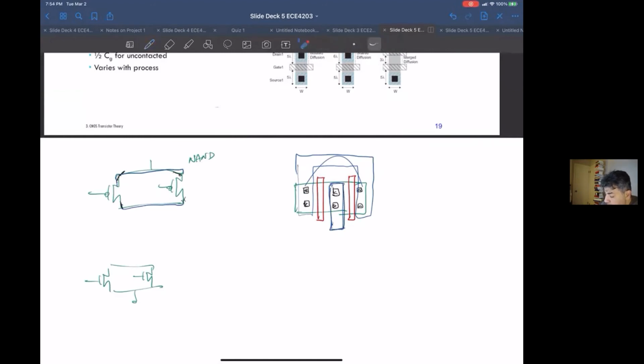Now, because the transistors are symmetric, I can make this the drain and this the source. Okay, so I can make this node, this node. So let me just redraw this thing. In the case of PMOS NAND gates, these would be their drains, and this would be the sources. So either I can make this merged node, or this and this merged node, or vice versa. I could make this the drains and this the source.